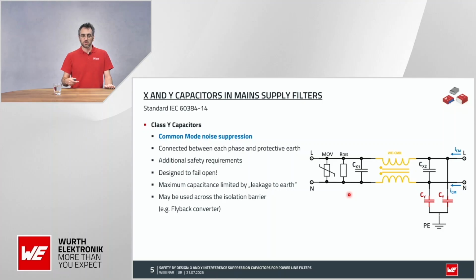Now, because Y capacitors are connected to protective earth, and normally this is also connected to the chassis, there are special safety requirements. The most important thing is that the capacitors are designed to fail open, and this is difficult to prove, but there is normally a reinforced isolation structure inside, as we will see later, that provides a method to achieve this.